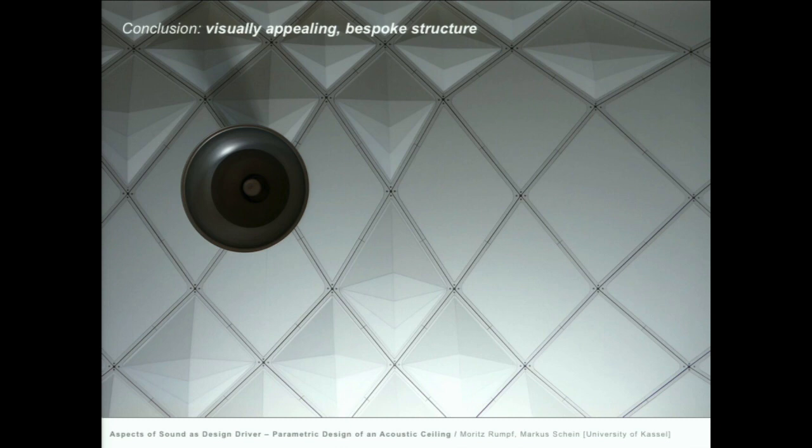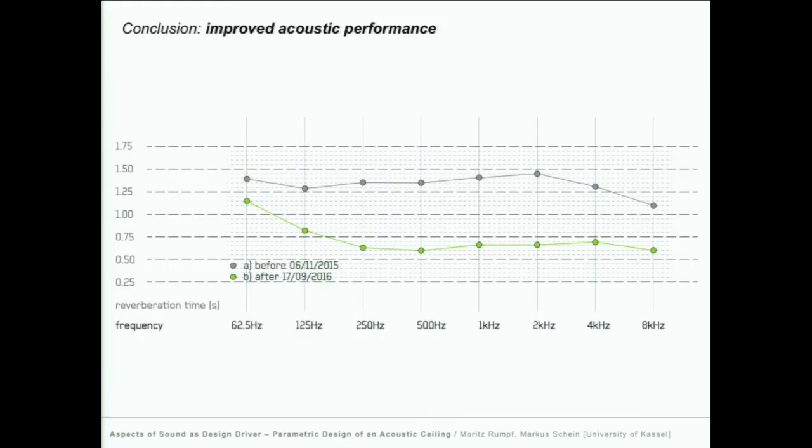Let me conclude. We believe that the project was a great success in multiple ways. First of all, it's an eye-catching structure, and we believe it represents Design to Production's philosophy. But also, hard facts: the acoustic performance was drastically improved. A standardized acoustic measurement after the installation revealed a drastic reduction of the reverberation time for the relevant frequencies, which is now below 0.7 seconds on average.